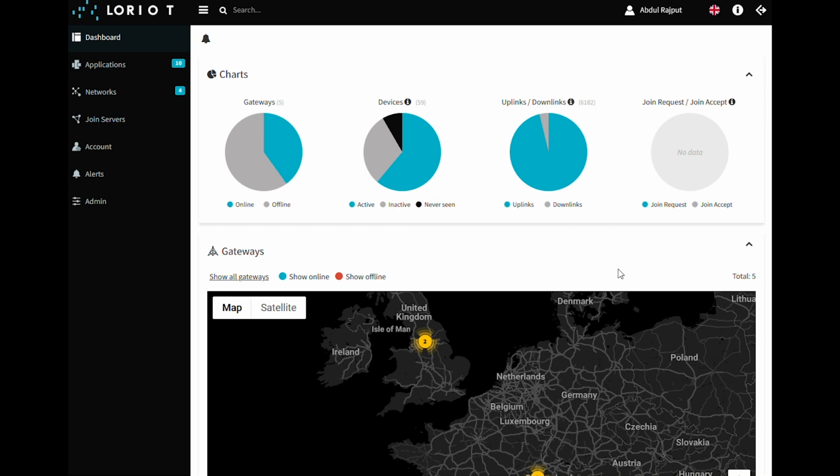Throughout this video I will cover things like how to troubleshoot your gateway and sensors if there are any issues with them. This can be useful if your gateway is not showing us online for some reason or is randomly disconnected.